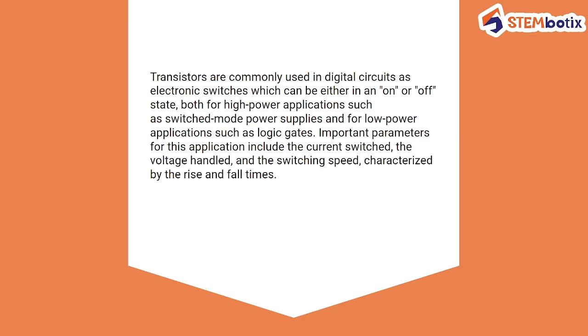Transistors are commonly used in digital circuits as electronic switches, which can be either in on or off operation, both for high power applications such as switched mode power supplies, and for low power applications such as logic gates. Important parameters for this application include the current switched, the voltage handled and the switching speed, meaning the speed at which it performs the switching operation, characterized by the rise and fall times.